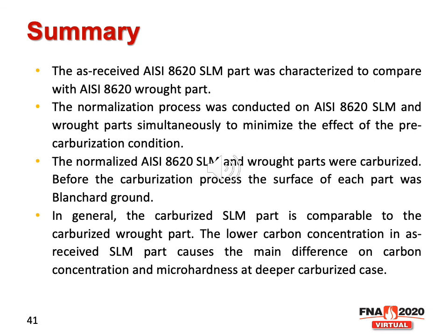In general, the carburized selective laser melted part is comparable to the carburized wrought part. However, the lower carbon concentration, which is due to the decarburization from the selective laser melting process, causes the main difference in carbon concentration and microhardness at deeper carburized case.